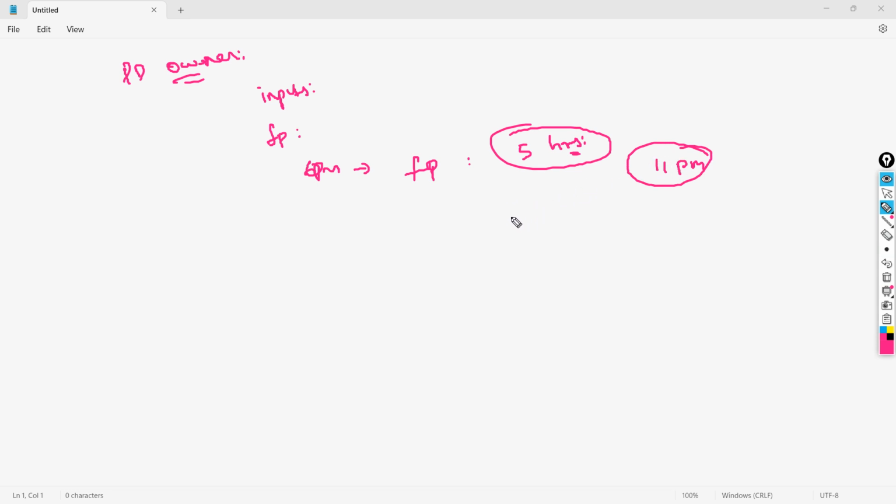Now you are going to fire the next step, called pre-place. This pre-place is basically adding the end cap cells, tap cells, and doing a couple of other important steps. Say this runs for the next 2 or 3 hours. It would be completed at around 2 or 3 a.m. Now you have to fire the next run, which is the next stage, placement.